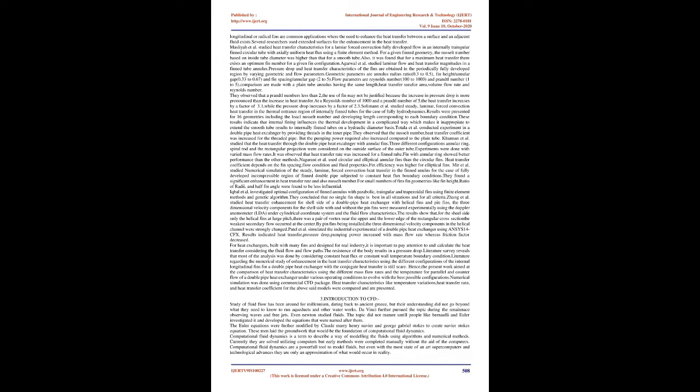1.4 Disadvantages of double pipe heat exchanger. Hairpin heat exchanger sections are specifically designed units which are generally not built to any manufacturing industry standard other than ASME code. However, TEMA tolerances are normally incorporated wherever applicable. Hairpin heat exchanger sections are not at all times cost-effectively competitive with a shell and tube heat exchanger. Proprietary closure design requires special gaskets.